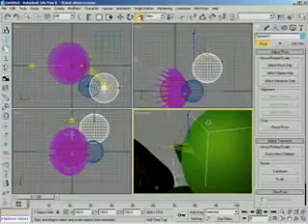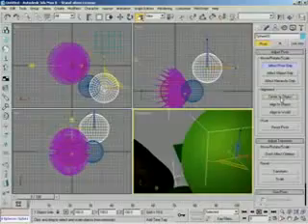Right. Now what's cool is they give us all sorts of features over here, if you will, in the hierarchy pivot panel section where we can affect pivot only, we can affect objects only, we can affect hierarchies only. I mean, the list goes on and on. And then we've got alignments where you see a big one, center to object. Very important. Go ahead and show them that one. Bink, back to the center. Yep.